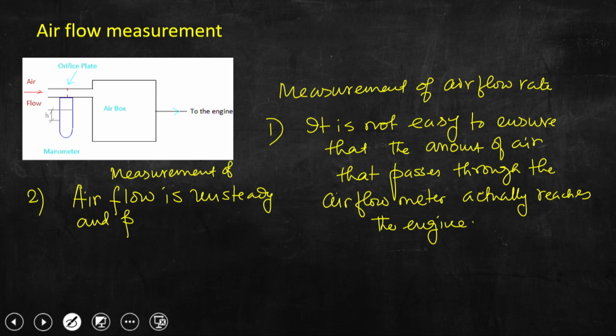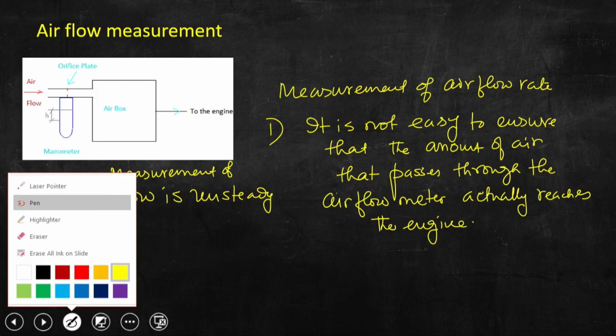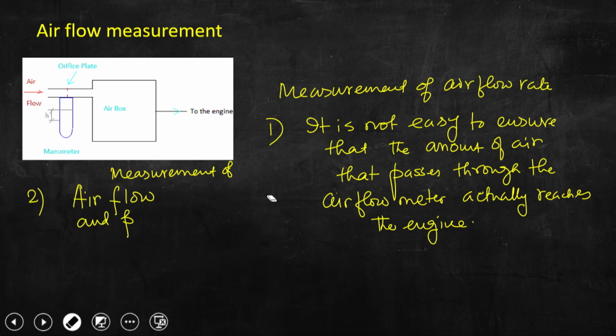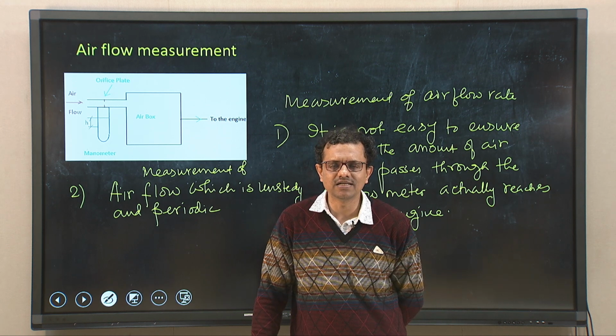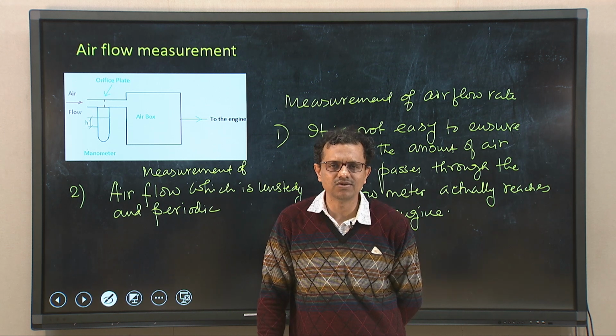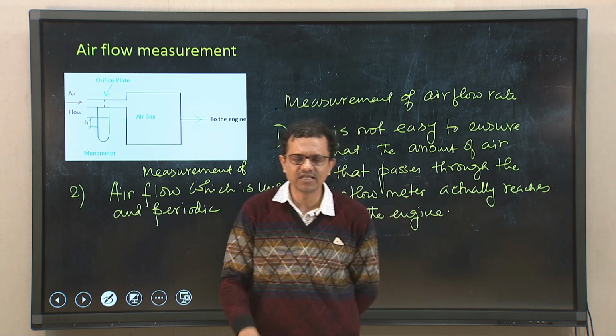So, measurement of air flow which is unsteady and periodic is a problem, because this is very common for any engine. As I said, air is drawn into the engine cylinder during the intake stroke, while the remaining strokes are not associated with air flow. So, this is highly periodic and also unsteady.